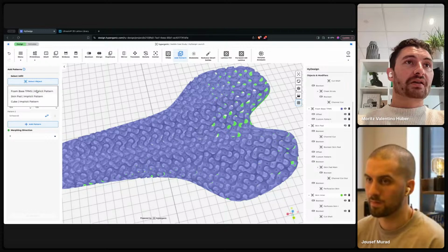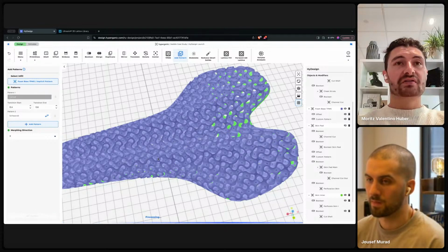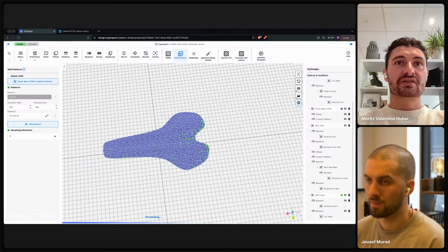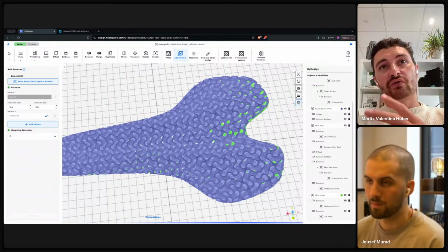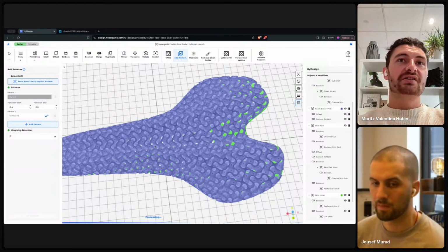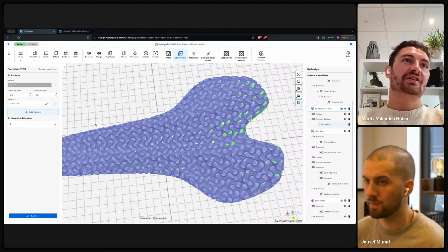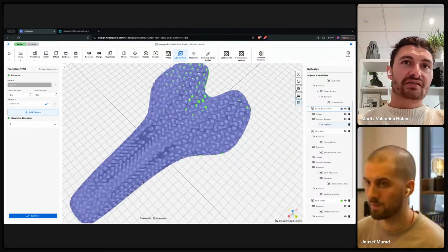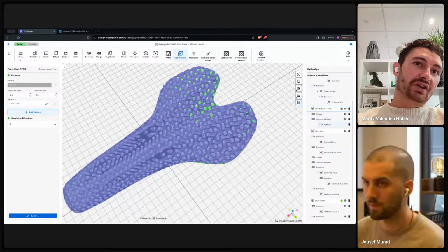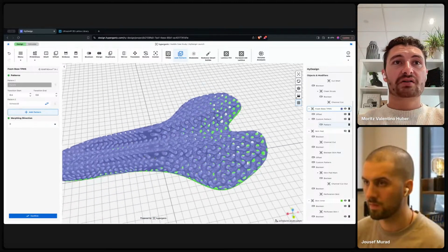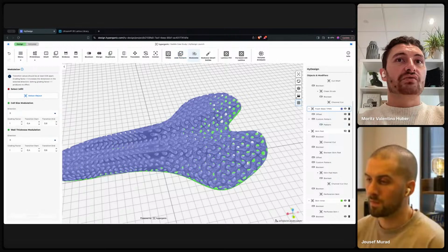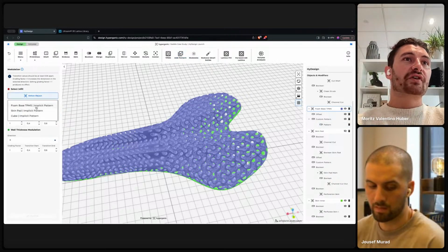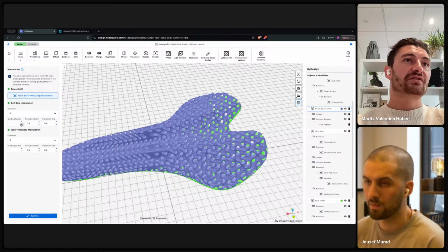And I will use this infill. This is going to take a short moment to update. So now the gyroid is going to transform, or linearly interpolate, into a Schwarz diamond pattern that potentially might be a little bit stiffer, depending on the cell size, and then you can even modulate that further. For example, also again in X direction. Let's modulate it by some value.